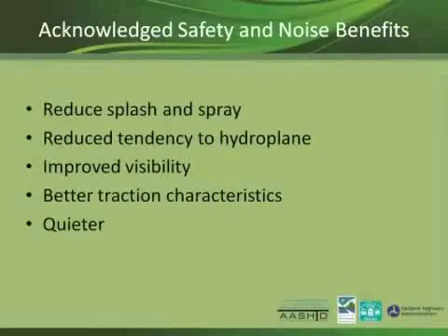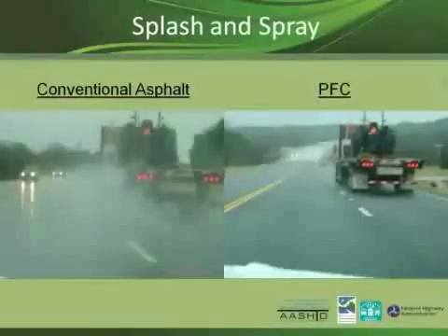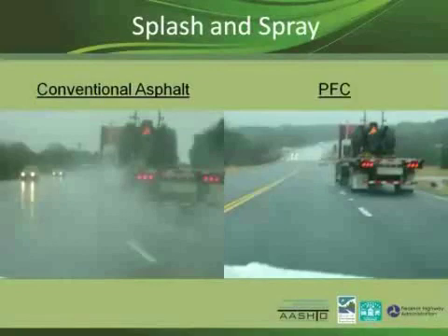So why do DOTs like it? The main reason is because you don't have the water on the surface of the road. You get rid of splash and spray behind vehicles. You reduce the depth of water on the road when it rains hard, so there's less hydroplaning chance. Are you going to screw me up by taking away my bullets, Eric?